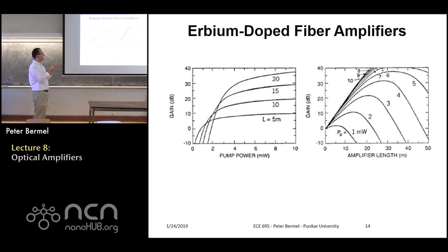But second, because the gain is so much higher, you can do two things: reduce the amount of extra noise being introduced into the system, because you have fewer amplifiers, and save money by building fewer amplifiers in general. You just propagate down the fiber for a much longer distance before you have to boost it, right? Because before with the Raman, we're only boosting about 10 dB, so you might have to keep boosting repeatedly to keep it going. But now you have four times fewer because you have so much more gain. So that's a big advantage.